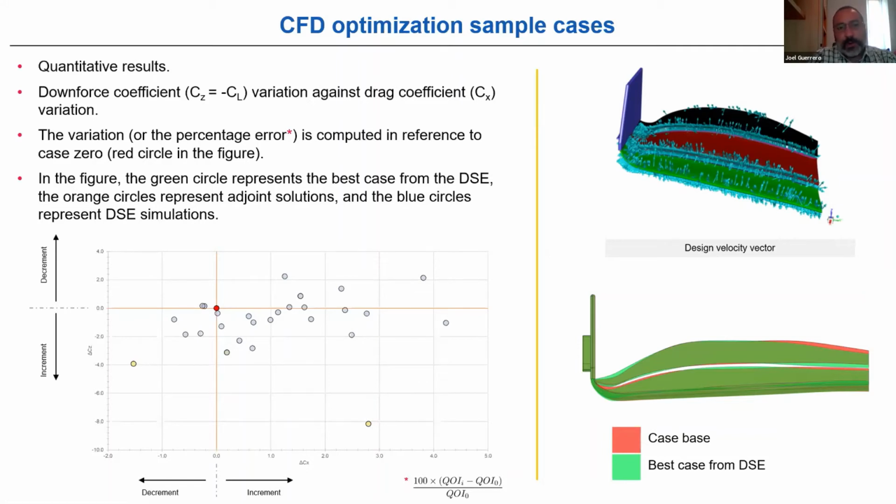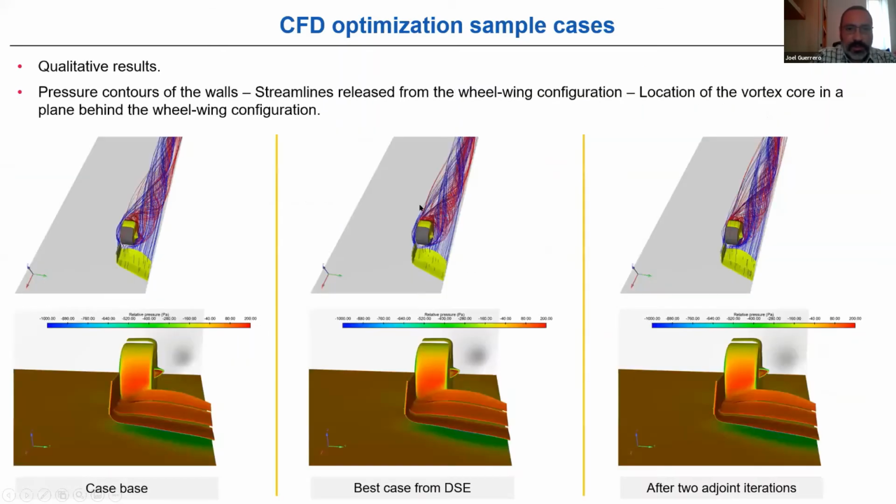And then when we were consulting with Marco Giacchi, he told us that this makes sense because it may happen in Formula One that you use this wing, for instance, for a slow track. You want a lot of downforce in a slow track, and this one would be for a fast track, okay? So depending on what you're doing, but see that the adjoint absolutely didn't give the best solution. And by the way, to get these two adjoint solutions, there were many iterations because the deformation proposed by the adjoint was too much. So we were a little bit outside those requirements that I showed you.